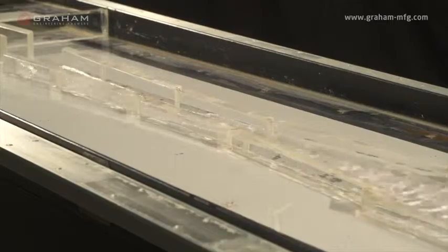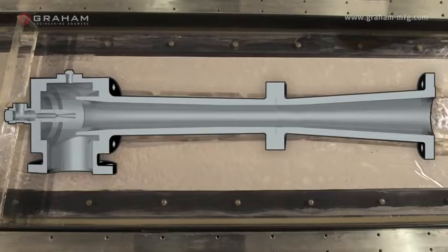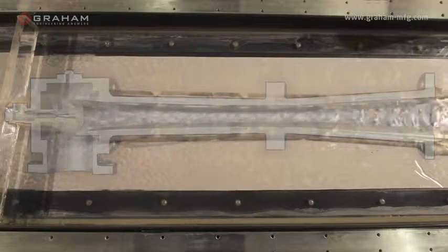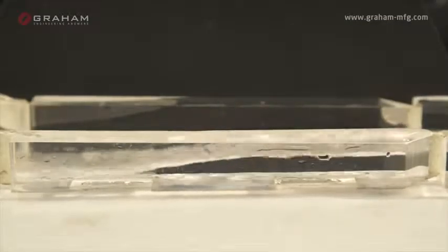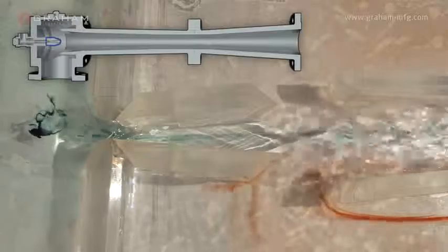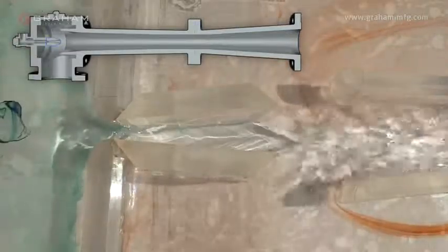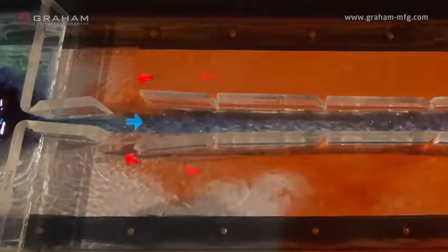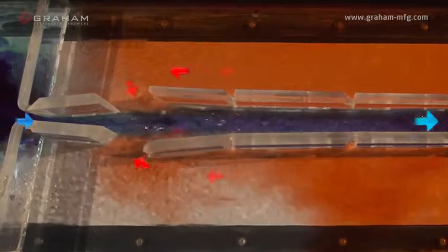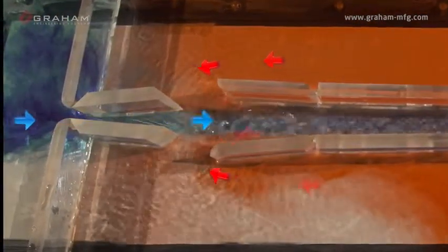To further expand on the principles of operation, here we have a two-dimensional hydraulic simulation of the flow through an ejector, which can be visualized on what we refer to as a wavetable. The height of the water in the wavetable is analogous to the pressure in an ejector. The motive nozzle expands the high-pressure motive fluid down to a pressure lower than the design suction pressure. As the high-velocity motive flow leaves the nozzle, it comes in contact with the suction fluid and begins to mix with it, entraining it as you can see here. The pressure will slightly increase through this section, causing the water level on the wavetable to rise.